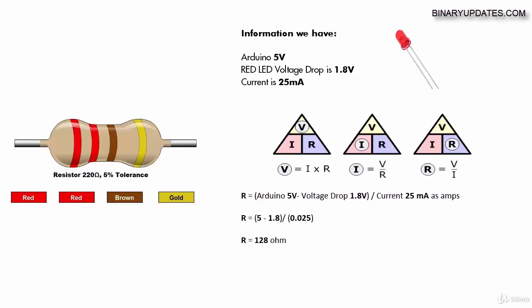Now you will think this 128 ohm doesn't make sense when we are using a 220 ohm resistor, right? Actually, what happens is when we do practical electronics as an engineer, we often look at practical easiness rather than theoretical correctness. And 128 ohm is a theoretical value, wherein 220 ohm is an easily available resistor value closest to 128 ohm.